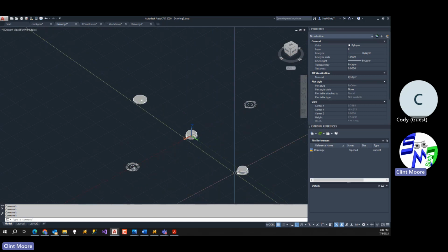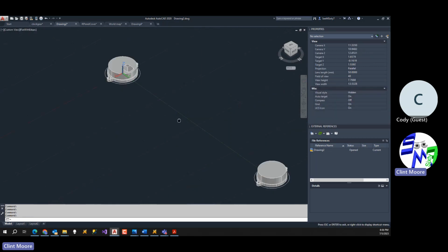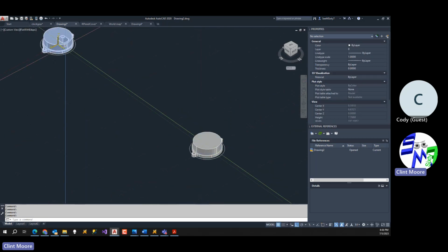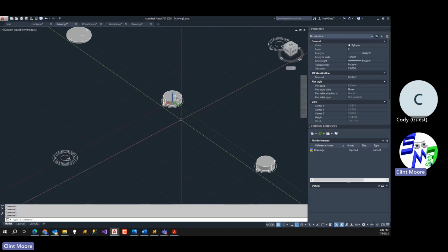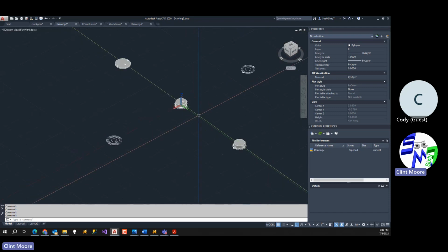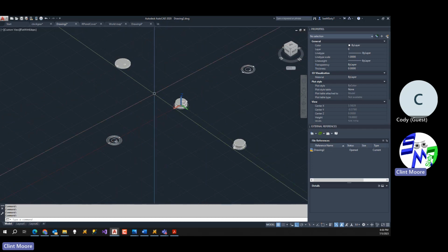But again, as I'm doing things, I'll actually just create copies in locals. Like this one here doesn't have the cutout for the motor to go in. And so I create little spots for myself to actually cut back and redo something. Because once you extrude an entity, that entity is gone. So then you just have the solid. So you don't have what made that solid extruded. So I usually keep copies of them so that it makes life a little easier for me to actually go back and say, oh, I just erased that, remake it, and then I can cut it again and then get it to where I need to be. So that's just a little trick that I use. It's not anything fancy or anything like that, but definitely useful.